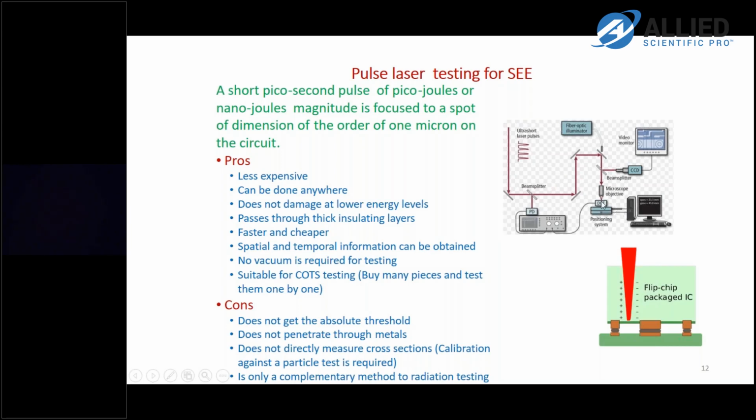positioning system. And what we have here, normally there are two cameras, a CCD camera and a near IR camera. They're looking at the device surface and also where the beam is, because the beams usually are in near IR. Very accurate positioning system of maybe about a 1 micron resolution. And you also have a fiber optic illuminator that shines on the whole device.